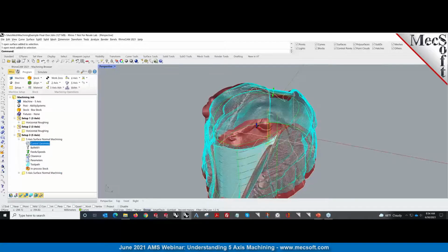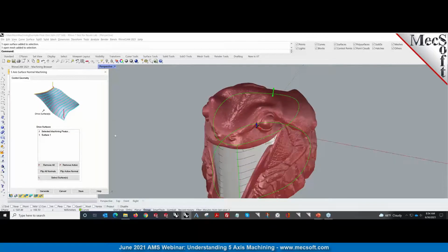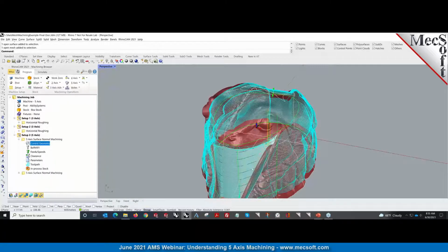Okay, yeah. So we talked about the control geometry briefly in the Toolpath method that I showed. So we need the surface to derive the surface normals on the cut pattern. So that gives us the cut pattern to position the cutter along. So that surface is used to define the surface normals as well as cut patterns. As you can see, that's the surface normal. We slice that surface to define the surface normal.